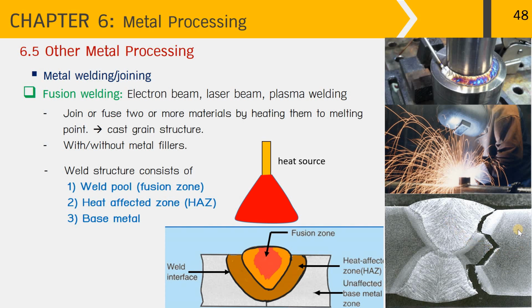So it's more likely that if we use the weld structure under mechanical load, failure normally initiates within the weld metal because of the cast structure that is larger than other areas, as you can see from this picture. And once the crack starts, it will grow very quickly and then finally cause the final or global failure.